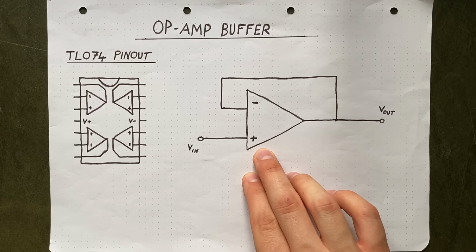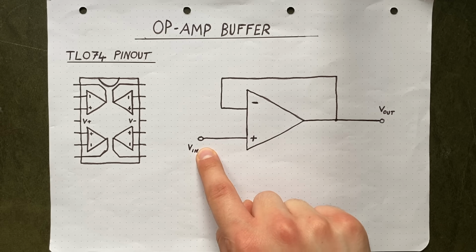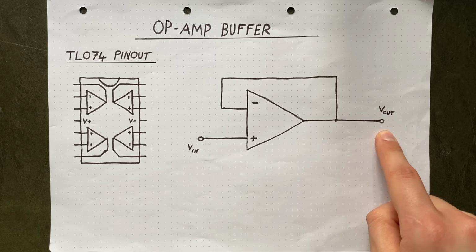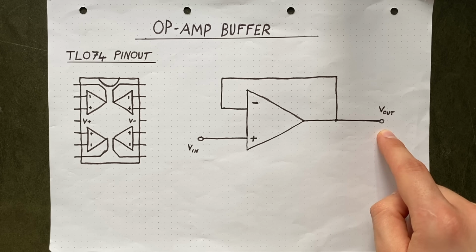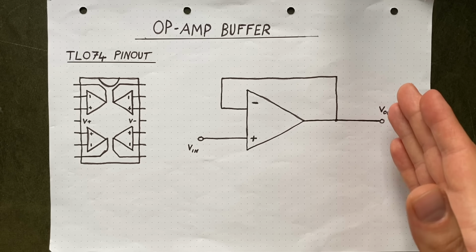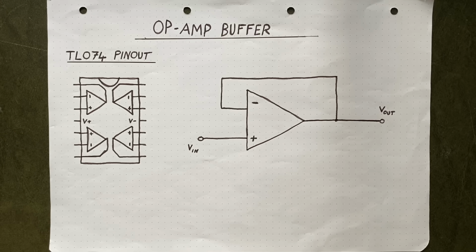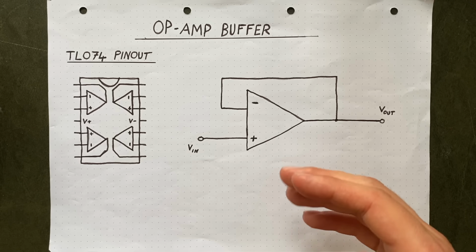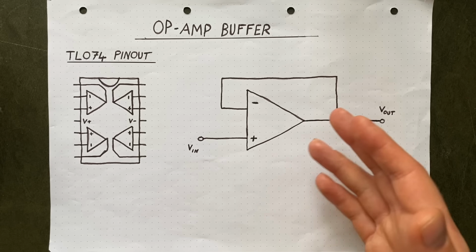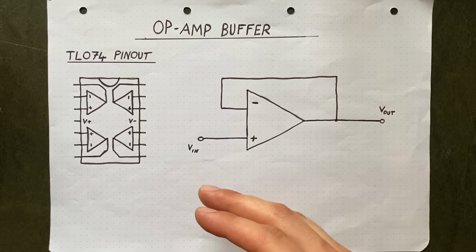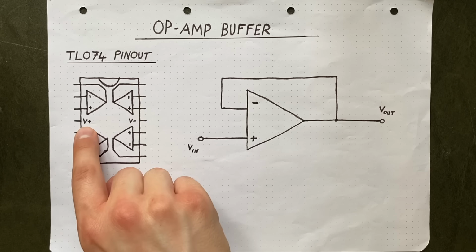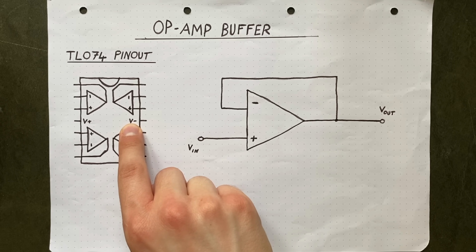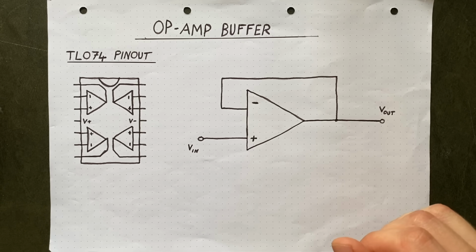This way we'll have our sensor on this side, while over here we'll get our copy of the sensed voltage levels. Sounds simple enough, but there is a catch. This is the pinout diagram for a TL074, which is 4 op-amps in one chip. Now with our 4106 we had a power and a ground connector, but with this chip there's power and negative power. What's up with that?